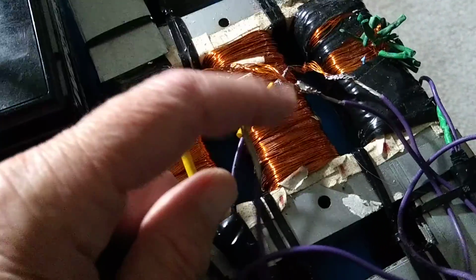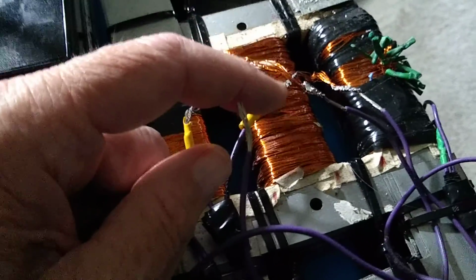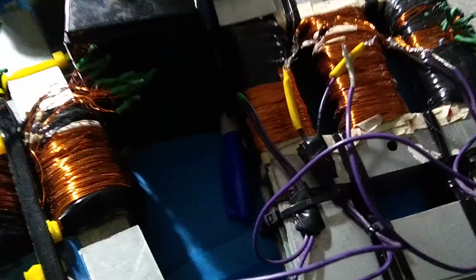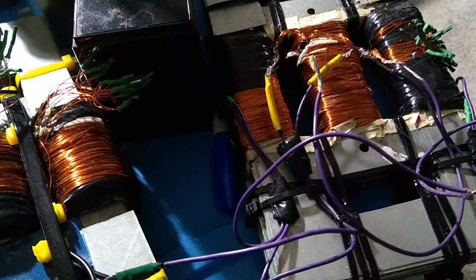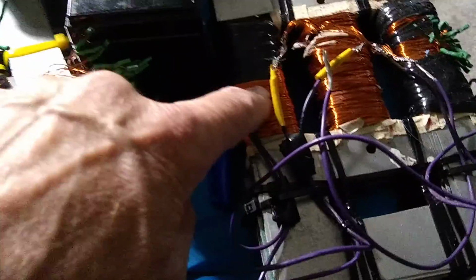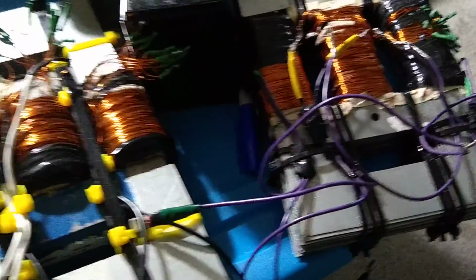So this is like a bifilar, multi-filar coil with 8 parallel winds that connect in series to another 8 parallel winds. So 8 wires together of 28 gauge makes a pretty thick wire here. So that's the primary I'm driving with 12 volts going each way, so it makes AC, and then it makes AC high voltage on the output with these 13 ohm coils here.